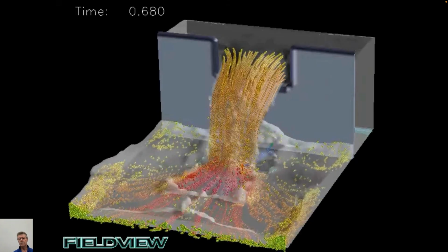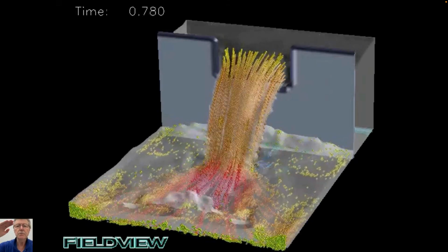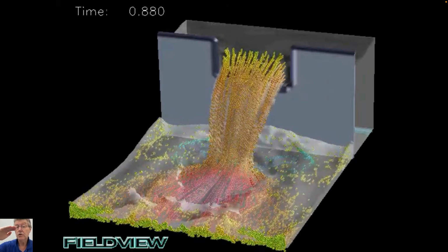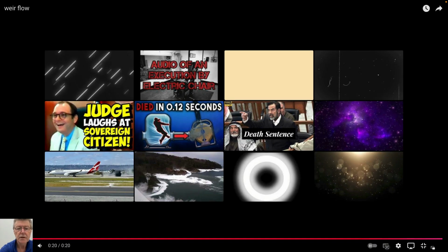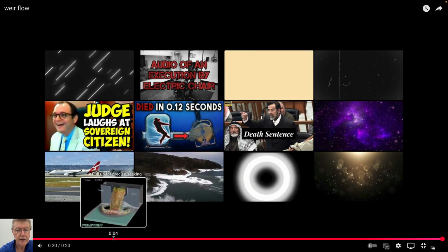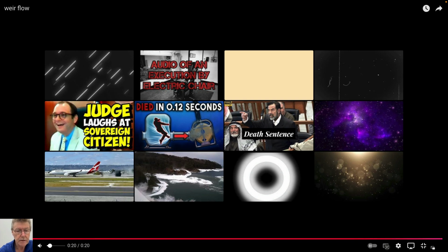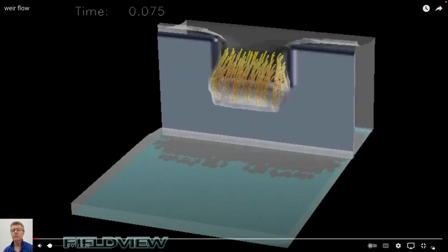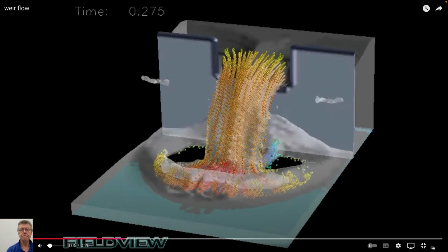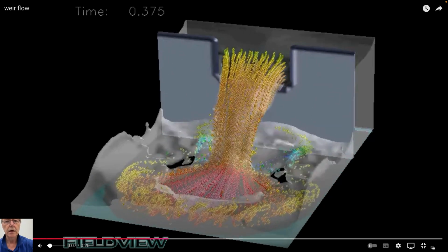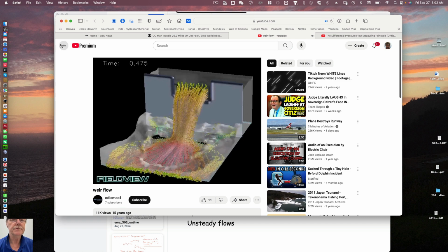Maybe the board has a cutout in it, and you measure the height to which the water flows across that board, and you can relate the height of the flow in the board to the flow rate. And so that's what we'll concentrate on today. So that's our plan.